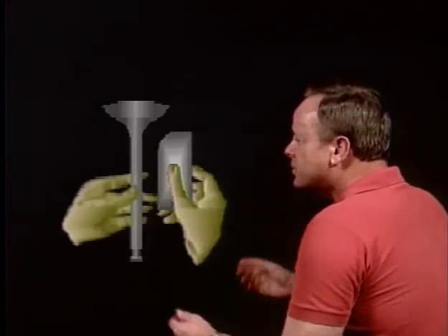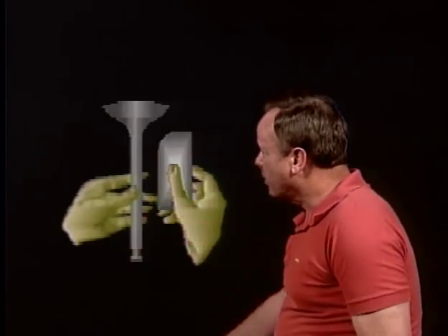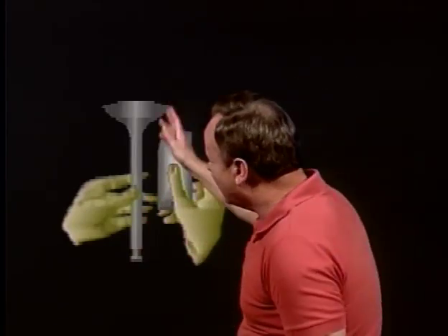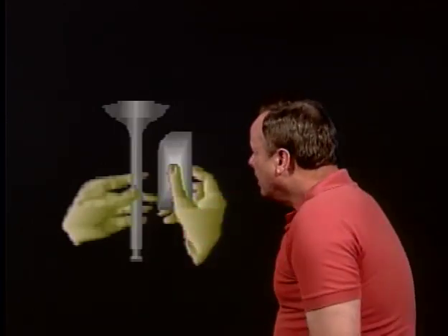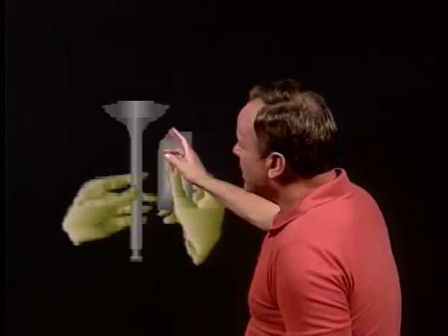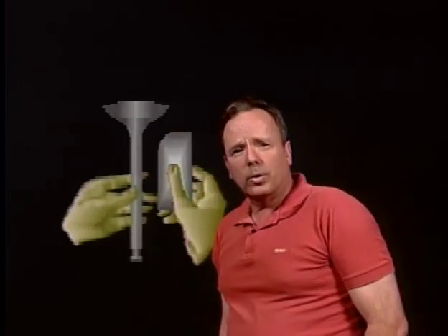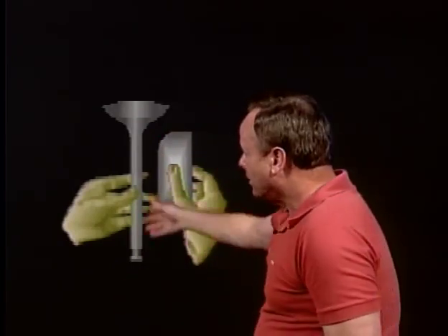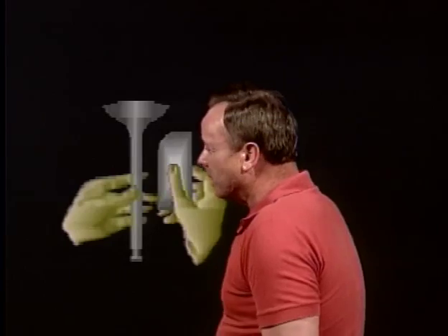You know, the exhaust valves in an engine take a real beating. They're where the action is. They're where the heat is. There's a lot of hot air going out around those things, and also just a lot of up and down movement, so they really take a beating. So if you're going to overhaul an engine, in real life, you're just going to replace the exhaust valve. You're not going to mess around with it. So therefore, the FAA asks you a question about this that is not real life. That's the way things go, folks. This is an FAA written exam.